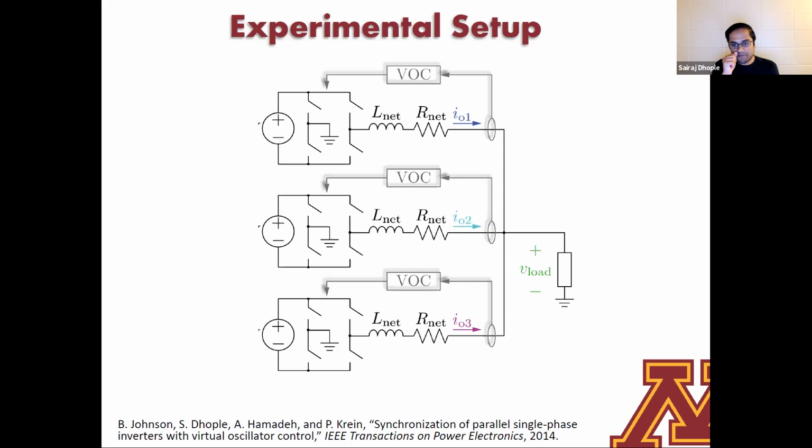So here's the first set of experiments that I'll present. It's a set of three. This was really benchtop stuff. A set of three inverters connected through inductor filters to a set of many different loads, and we'll cycle through a few different loads to see the behavior of this particular control strategy. Each of these has its controllers implemented using this virtual oscillator control method. There's no communication between individual inverters.